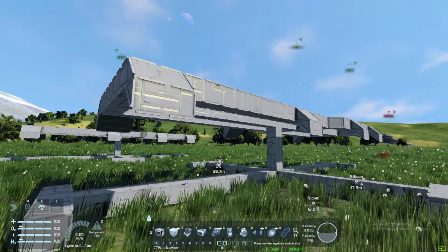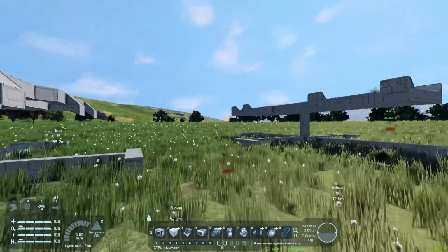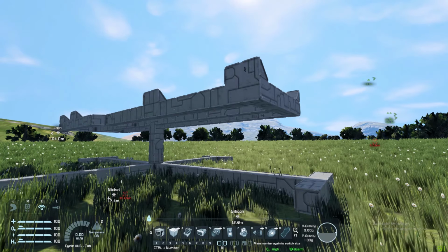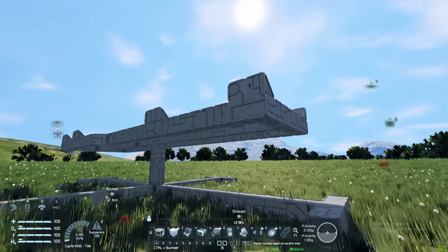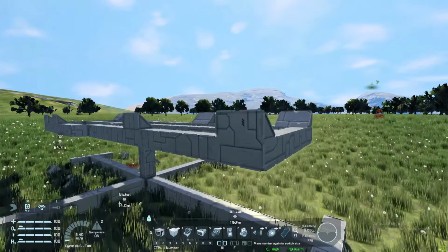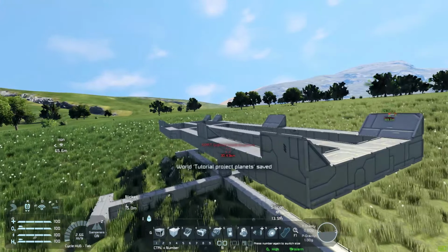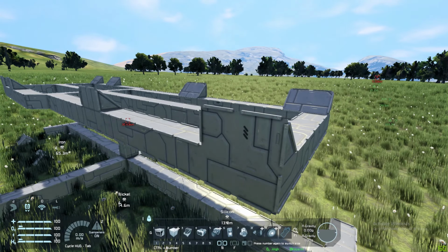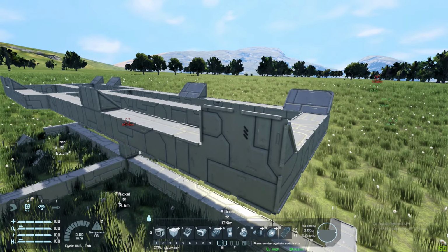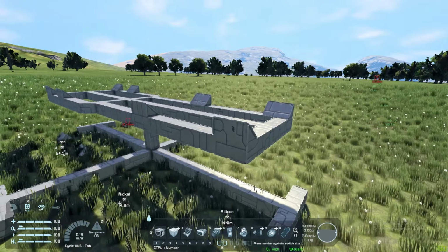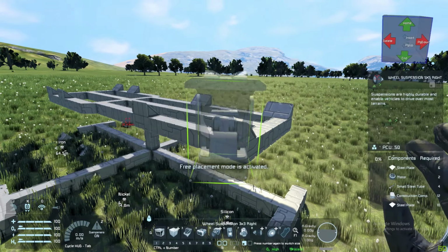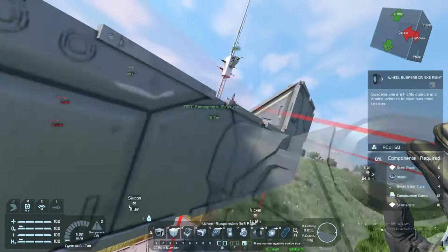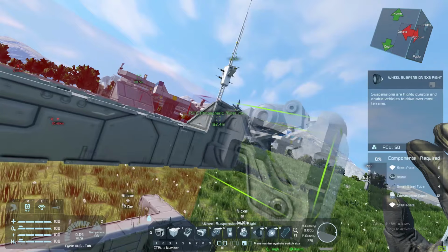mounts. You can use the different designs you see here to lower and higher the ground clearance. You always must consider ground clearance. So in order to get larger or smaller ground clearance, I use these. Now the ones on the top give a lower profile, so the frame will be lower to the ground. You can see when you put a wheel on it, okay, the wheel is actually higher than the frame.